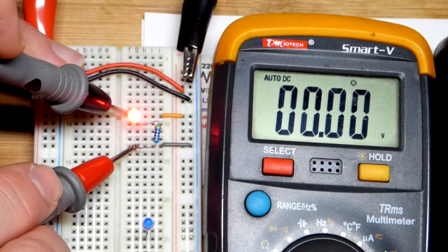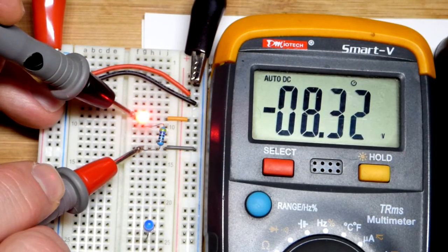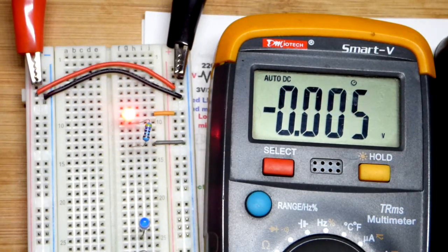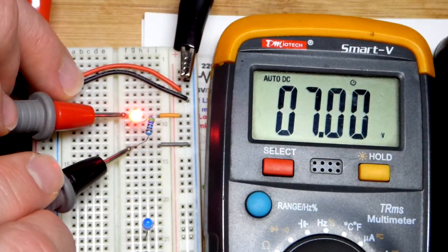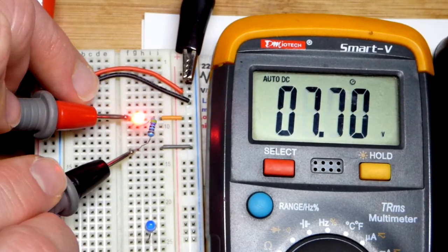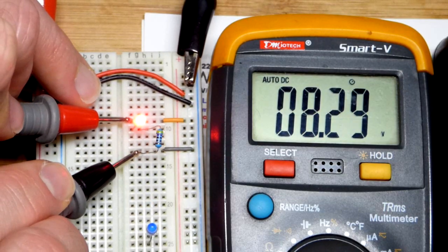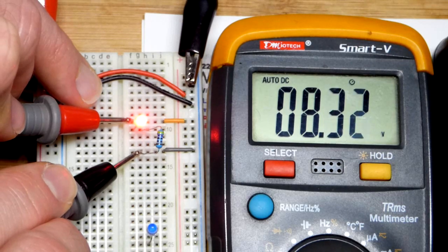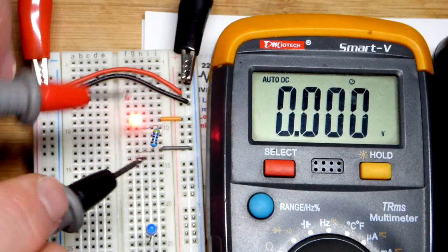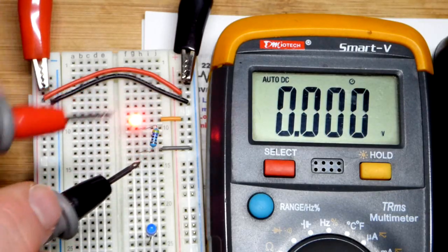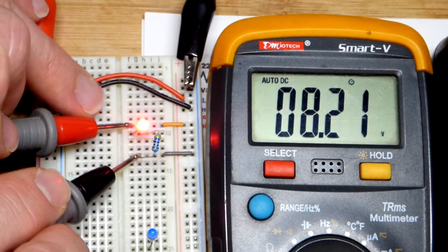Again, this is a cheap board. We have a bunch of connections. I got the probes backwards. I didn't mean to do that, but that's fine. You just get a negative voltage. But in any case, this breadboard's cheap, doesn't make the best connections, and everywhere you have connections there's going to be a little bit of resistance, at least a little bit. And there you can see we're losing a fair amount of voltage once we finally get to the load. But it's close to a 9. And again, it's kind of a cheap board. These are thin leads on there. As I press on them and kind of shift a little bit, it's going to affect the connection. Something to be aware of. But again, got about 9 volts.